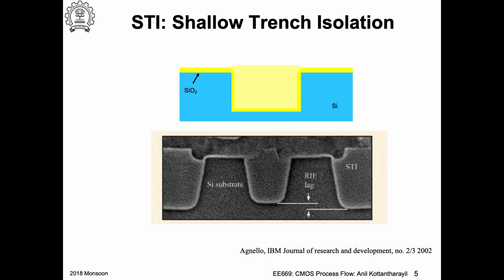Something that they've actually shown is interesting: if you have a very narrow trench, the aspect ratio of this trench seems to be 1 or larger, so the depth to width ratio, in the middle one. What they're showing is that they're not able to etch it as deep as the wider trenches. This is called an RIE lag.